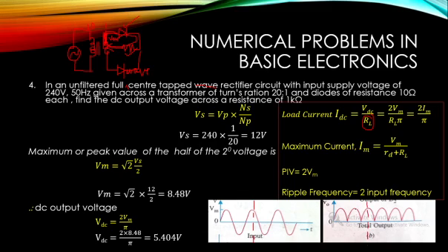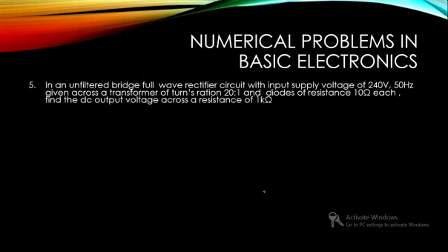you can see since D1 will be forward biased in the first positive cycle, and during the negative cycle D2 will be forward biased in the same direction, and hence you will get two or a continuous ripples. So here you can see for the same time instant there are two peaks involved. So what would be the frequency? It would be 2 times the input frequency. So it would become 2 into 50, which is 100 Hertz. So all these could be asked.